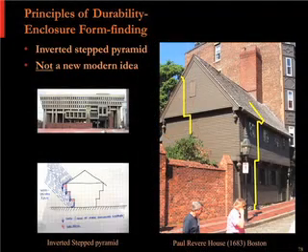When you think about the inverted stepped pyramid, you're sheltering the water, so in that little sketch, all those red areas are never seeing the rain, even in a 45-degree rain, and then each of those areas overhangs the one below. So the blue arrows are dripping off water, but even more importantly, they're not throwing it back onto the building somewhere else where it'll just be moving the problem around. By stepping out, every drip point clears the next one.